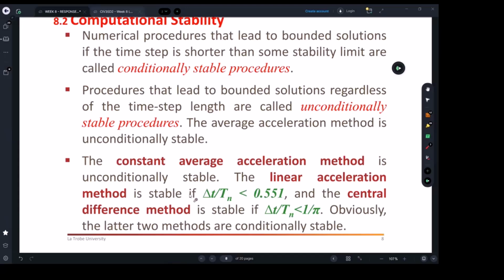If you start seeing the results are not changing, the stresses or deformations of your building are not changing. But remember, as you go smaller with your mesh, you will have more elements. So it's going to take more time for you to do the calculations. But nowadays, it doesn't matter if you have an extra 3 minutes to do the calculations, really.